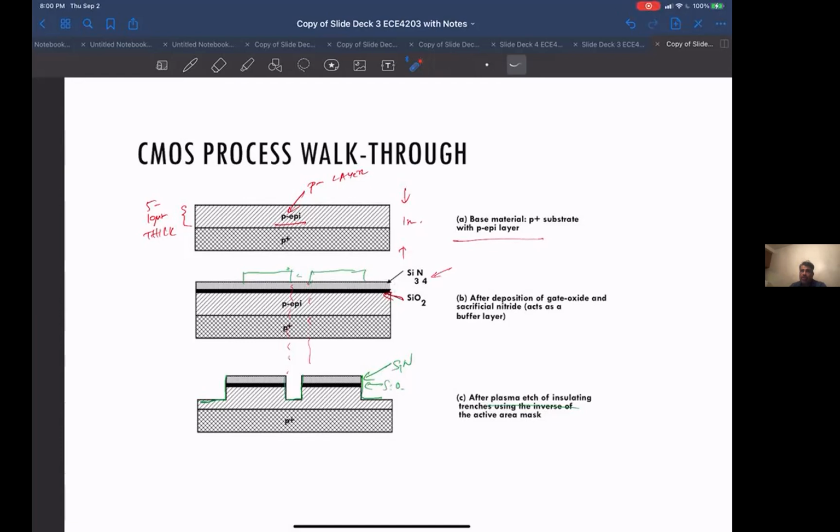So your early steps can be relatively hot, but your future processes have to be step by step less hot. Otherwise, if your 100th step is at a temperature that's going to mess around with your 5th step, you're in deep trouble.